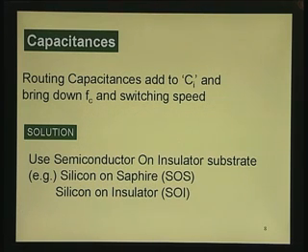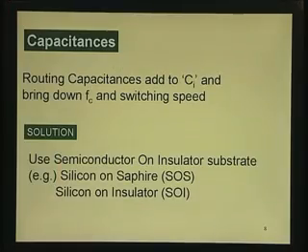The other thing that we will have to be concerned with is that the mobility is not so much dependent on frequency, okay, because in the frequency that we talk of, they do not vary. They are dependent on field, okay, and temperature. If you go to a very high field, they will be changing. Otherwise, with field it does not change. Okay, I am sorry, with frequency it does not change. That is a constant. In fact, even at high frequency they use that concept. Okay, constant mobility. Because all those equations that one develops are based on the constant mobility with frequency.